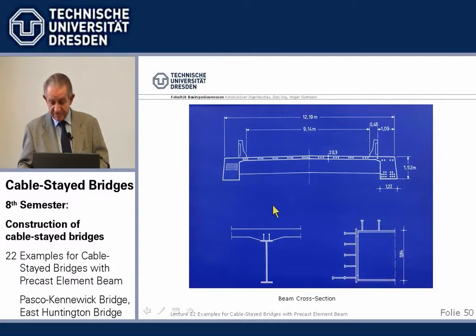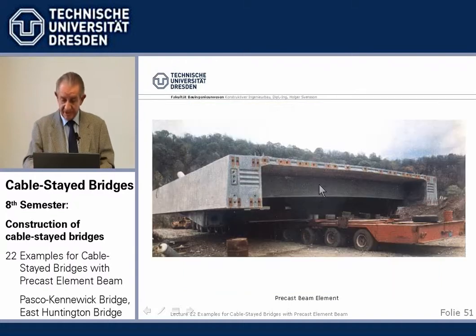Since we have, due to the rotational stiffness, a certain fixing of the cross girder, we have tension here from a positive moment, and in order to carry that we used double stock shear studs, which means we welded one on top of the other shear stud, which permits you rather safely to introduce tensile force via shear studs, whereas normally these only take shear, as the name says.